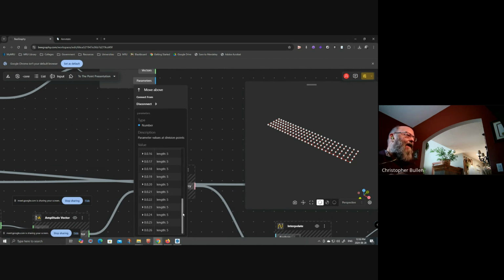There we go. Okay. This has got 27 in this list. Well, what do we have 27 of? We have 27 points going across this way, and in each one of those, we have 5 values. So this is a list of all of these lines going in the opposite direction of the span. I need to take this list and make it so that instead of 27 lists, I have only 5 lists that have 27 items in them, not 27 lists that have 5 items in it.